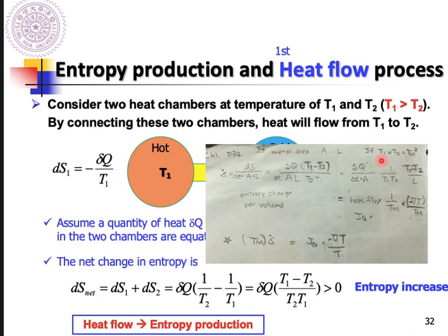T1 almost equals T2, so I can make this assumption. So for T1 and T2, we use Tm squared to substitute. Then I put a 1 over Tm here and the other Tm here. And for this T1 minus T2 divided by L, I will put a temperature gradient term here. And the heat flux is passing through this one.